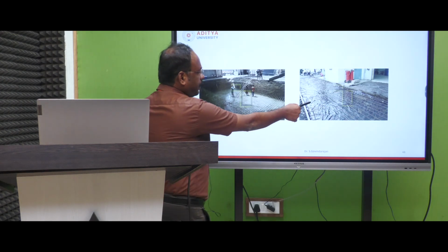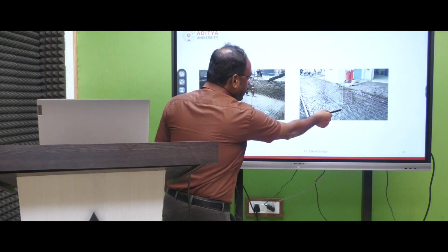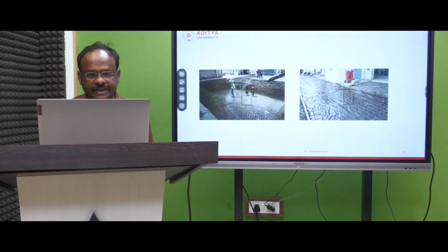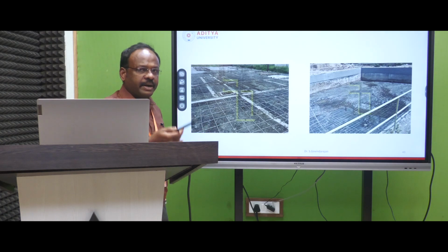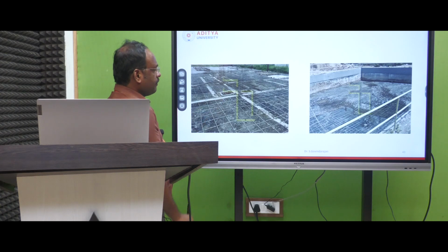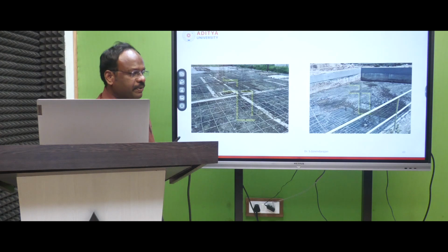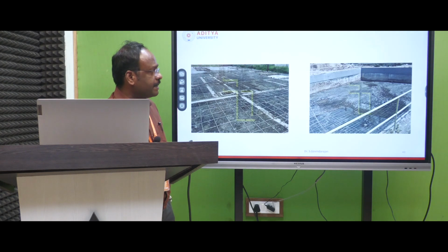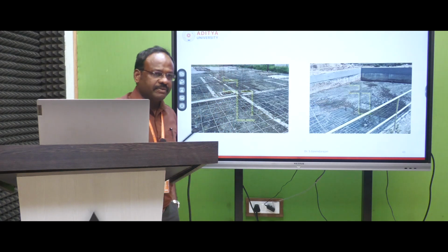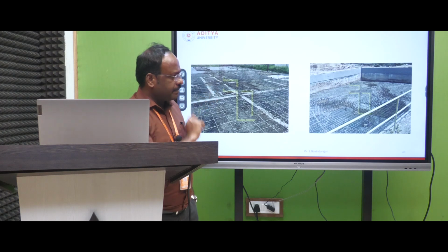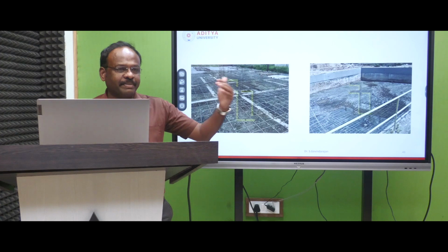At the same time, for the road pavement, as I already said in the previous slide, you replace it with fiber reinforced concrete only, right? This is for the second diagram. And another one is at the roof level also, instead of our normal reinforcement, you place fiber reinforcement. At the same time for water leakage, like in a water tank or sewage water treatment plant, you also place fiber reinforcement, because it will resist water leakage. That is the purpose of using fiber reinforcement. These are some of the diagrams showing the structures where the fiber is used.